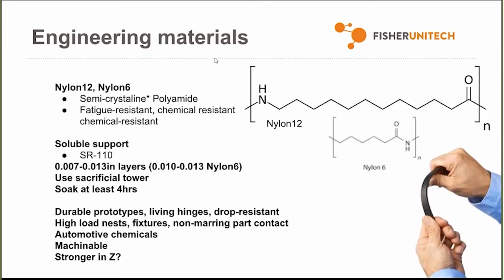So for that reason, although it's not mandatory, I would suggest using a sacrificial tower. Tick that box in the options in GrabCAD Print or in Control Center in the options menu. Basically, with that sacrificial tower, it'll help prime the tip by extruding immediately before it gets to the part. It's sort of an intermediate step between the purge bucket, purge position, and the actual part, and it'll help to catch that drool.